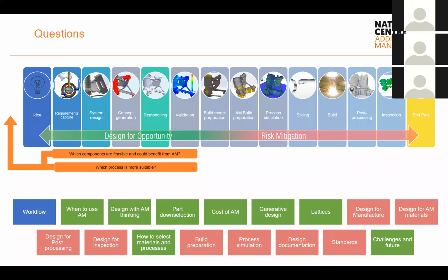Well, with this workflow, there will be some other steps. So, for example, in jetting materials like Desktop Metal or those kinds of things, after the build there is other post-processing happening afterwards, where the part gets modified. For example, removing the binder in the part, and we need to think about it as well in the remodeling steps. So really, the example that we can see here is powder bed fusion, but in terms of the overall steps it will be very similar.